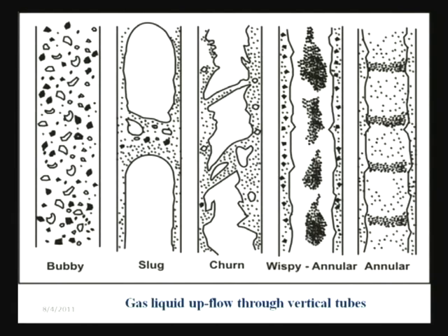So, that very nice periodic flow phenomena disappears altogether, and what we get is a totally chaotic and random flow phenomena, where there are irregular chunks of gases and irregular masses of liquids flowing up and down in a totally chaotic and random manner. You cannot predict the distribution. It is simply a chaotic and random distribution, and that is termed as the Churn flow pattern.